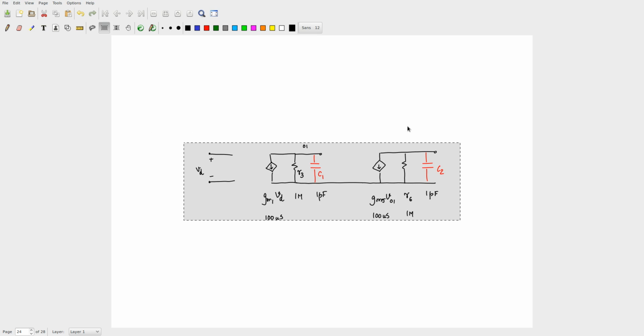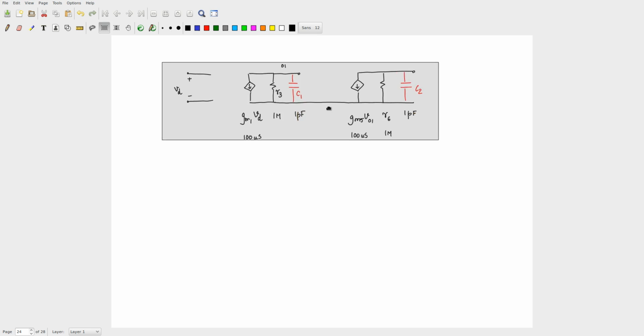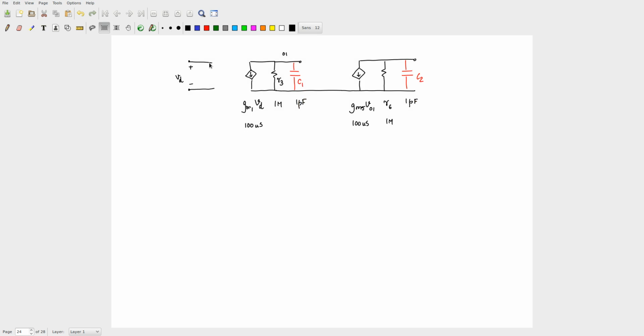So with the same circuit, I am still not going towards compensation, but I want to make zeta equal to 1. So what can I do? Assume that I am going to add a capacitor here. Okay, let me say I add a capacitor Cc like this, or yesterday I had called it C alpha. So if I add a C alpha like this, and you want a zeta equal to 1, what can you do? How do you calculate it?